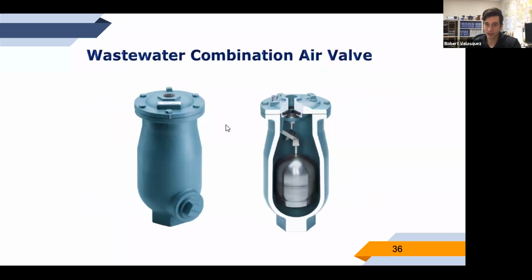This here is the exact same thing, but for wastewater. So again, we've elongated out the body, keeping the wastewater away from the orifice and away from our mechanisms. But the same thing where we've got a check valve here in the top, and then there's going to be a small orifice through it that this ball and float and pad will be opening and closing to continuously release air during system operations.